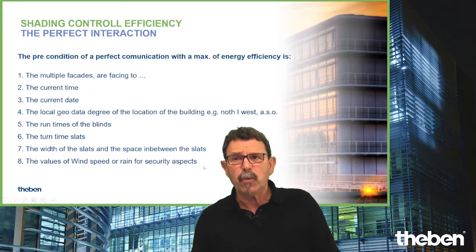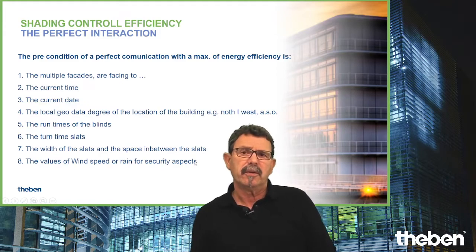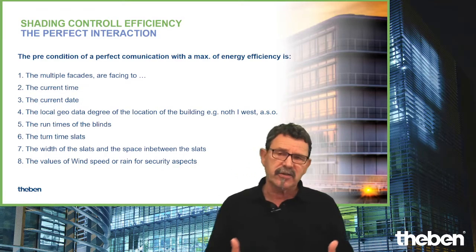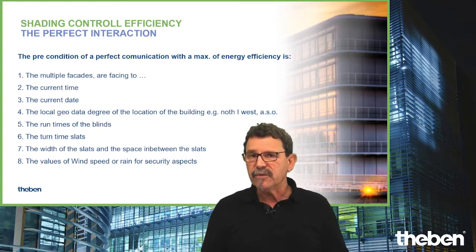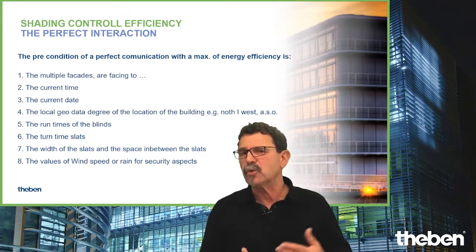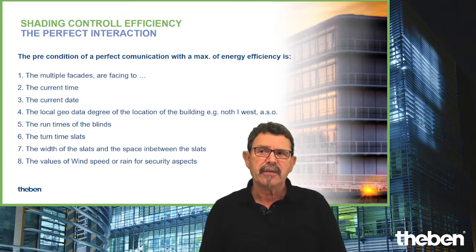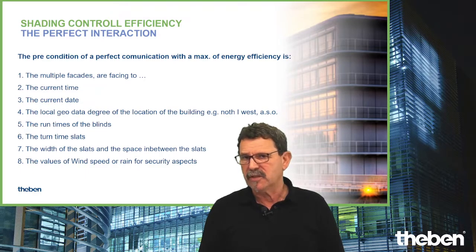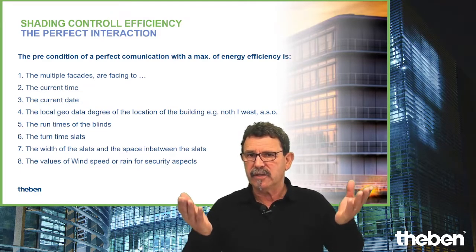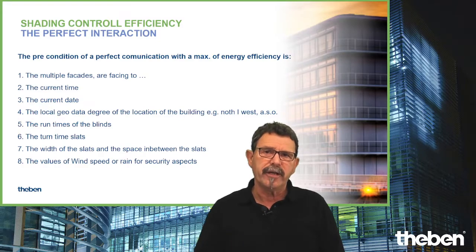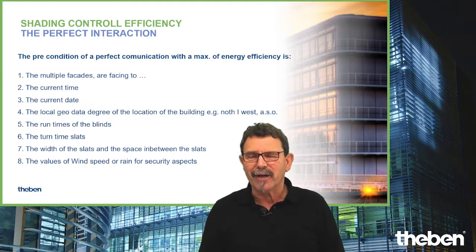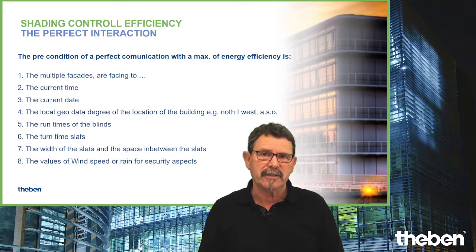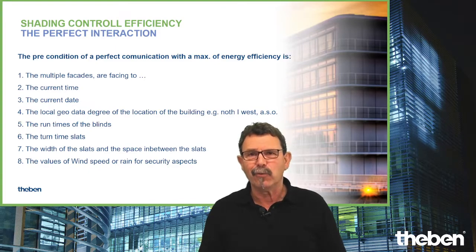And definitely I want to remind you, when you do blinds control, don't forget to set up the alert function. That means if the wind speed is too high, all the blinds are raised, avoiding that they are destroyed by a heavy storm or by a heavy wind. Don't forget that. Otherwise, it will be rather costly.